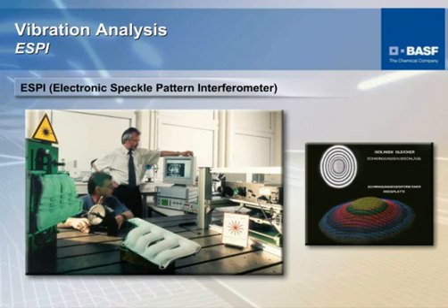And basically what it does, it enables us to lay a grid over the structure and extract the surface depiction of that structure readily. So basically we can kind of take an image, assess what the vibration level is or the movement, right at the surface. So we can excite the structure, and based on that we can get a representation of that structure, and it moves very quick.